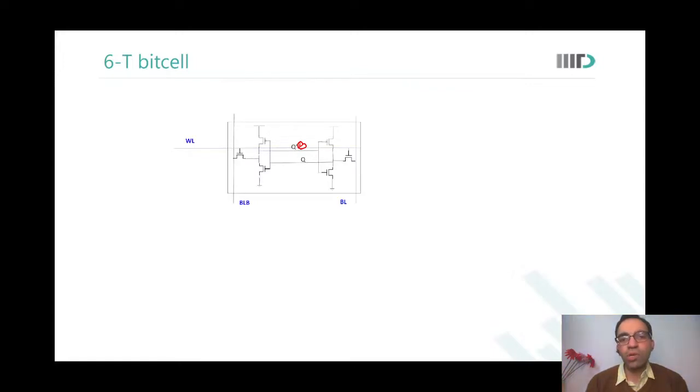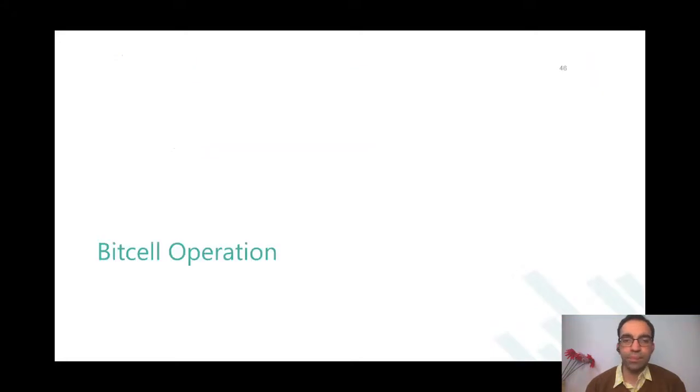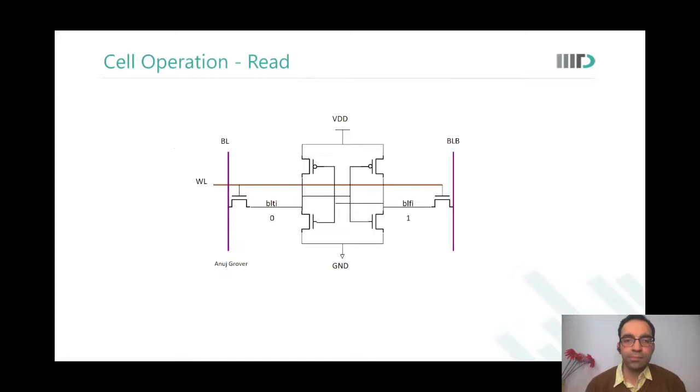So now how do you read and write into the memory cell? See, until the time it was a D-Latch, you knew you would get a 1 at the Q pin and a 0 at the Q bar. But now Q and Q bar are no longer accessible. I just now said that word line, bit line, and bit line bar are the only ports that you have. The user can no longer access Q and Q bar. So how does he read? Through WL and bit line?